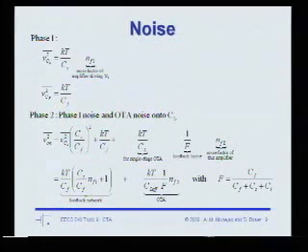So those two terms we discussed last lecture. And last lecture, this is where we stopped. And this now makes perfect sense to you guys, right? No need to explain it. The actual amplifier now is going to contribute a noise kT over CL. This feedback factor takes into account the difference between the noise of the device and its output impedance, right? Its output impedance has an extra factor of F in it. And then this extra factor is kind of all the dirtiness of the amplifier, right? The amplifier has maybe a cascode in it, maybe it has something weird, maybe it has a PMOS current source, and that's going to add another extra factor of 1 plus V*1 over V*2, you know, all that stuff.